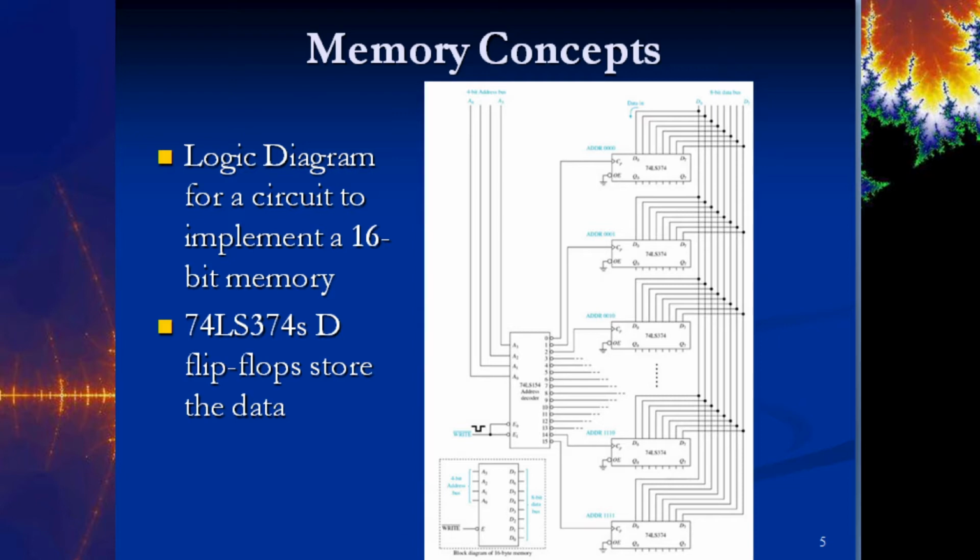You'll notice in this example that all of the D inputs are tied to the same 8 bits of a data bus. Once it has the appropriate register chosen, whatever that data bus has on its inputs is going to be passed through to the Ds, and then locked into the flip-flops for the Q outputs. So the timing of all this is very, very critical.